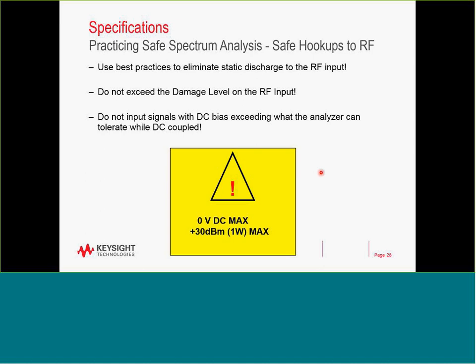Very, very important, especially if you borrow some equipment from DMC or from anyone, or even if it's yours, is to make sure that when you're connecting something to the front panel of the equipment, you go and read that little yellow sticker that tells you what you should and should not do. These equipment are static discharge sensitive. And people say, oh, I've done that 100 times and it didn't damage the equipment, and this time it did. Well, static discharge will not automatically destroy the equipment in many cases. The addition of multiple of those little charges will finally get through it.